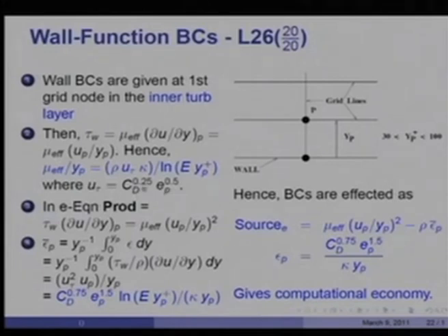You will recall that we had shown this for the turbulent part of the inner layer, and therefore, u tau can be estimated like this rather than from mu du dy equal to 0, because we are not computing up to this point. We are only computing from this point onwards. U would be, of course, obtained from the RANS equations at this point.